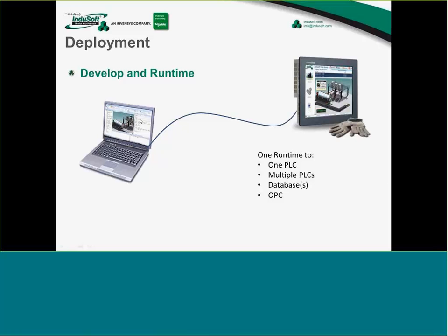But basically, you develop and configure your project on a development environment, and then you run it often on an industrial PC, but it doesn't have to be on an industrial PC. It could be a laptop, a desktop, a server. And that one runtime can usually communicate to often a PLC or a database. Could be multiple PLCs. Depending on your license level, you can communicate to multiple drivers simultaneously.